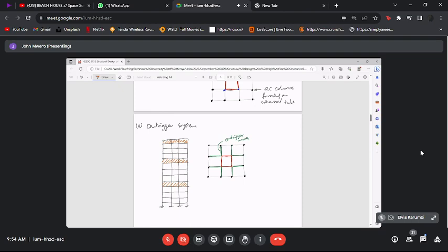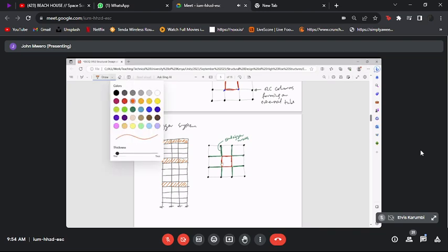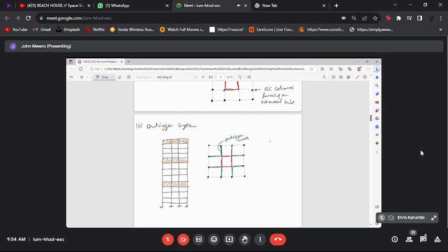These walls are basically like deep beams that are transferring the shear from the central core to the external walls. And the way it does this is similar to the outrigger boats. You know, the small boat that has got a pole that goes across, and it has a sail, and this pole has got some timber planks there.